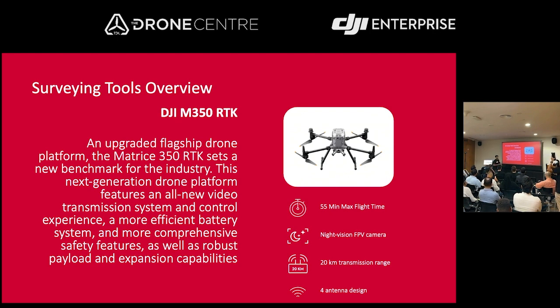So the Matrice 350 is an improvement over the Matrice 300 drone with a key improvement of the night vision FPV camera, in which you can work in the nighttime without worry about hitting something, because the first person view camera is an added obstacle avoidance sensor. And the M350 drone is upgraded from 15 kilometers FCC range to 20 kilometers range in an FCC area. With the 4 antenna design, you are expecting it to be more accurate and get the TimeSync 3.0 data, in which the controller, the drone, and the payloads are synced together to get the most accurate data.